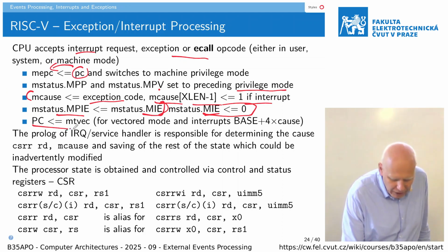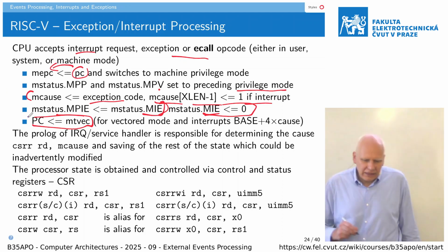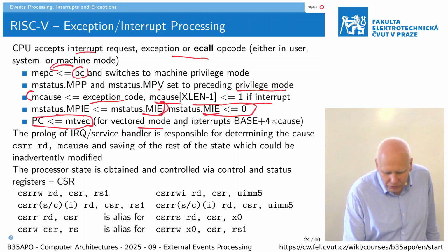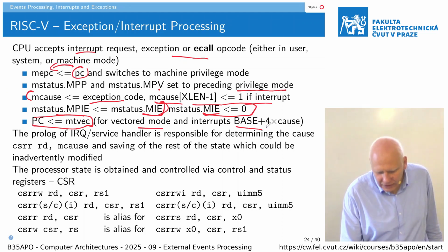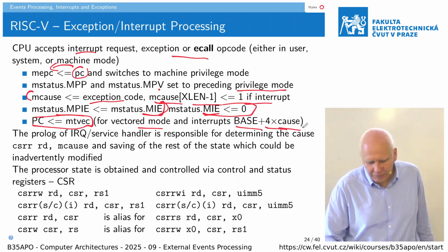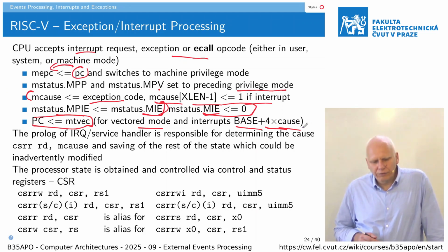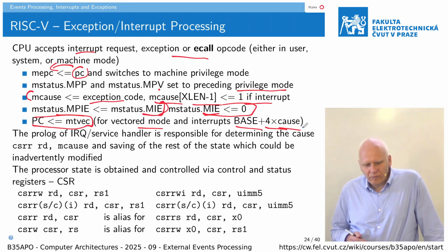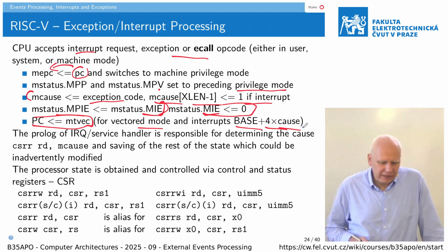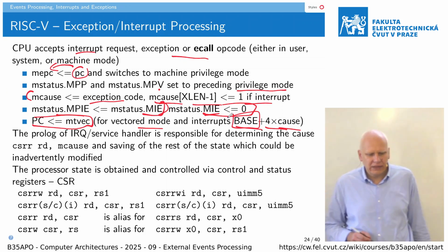And the program counter is set to the mtvec. In vector mode, it is set to the base plus 4 multiplied by the cause, in the case that you have that vector mode. But external interrupts are in this case still directed to the base address.